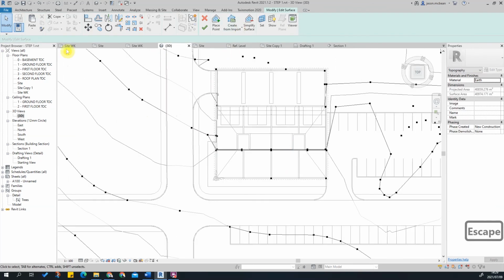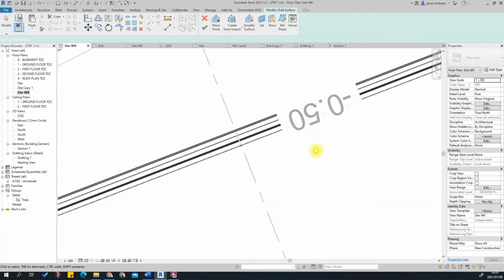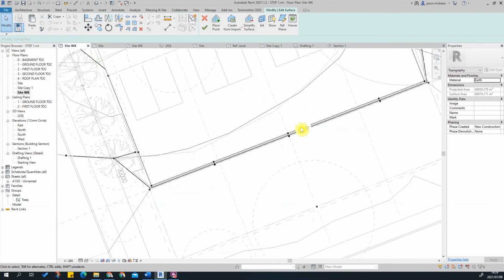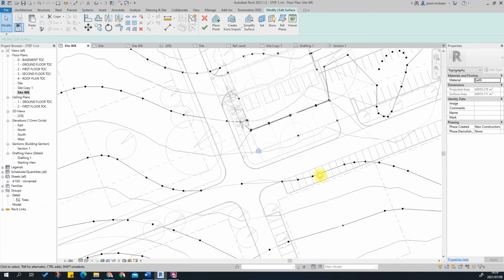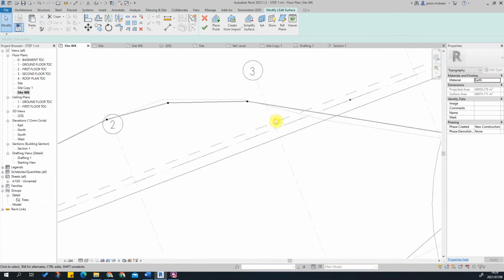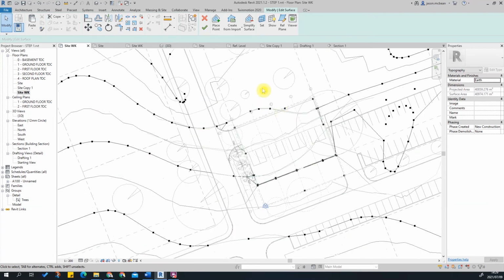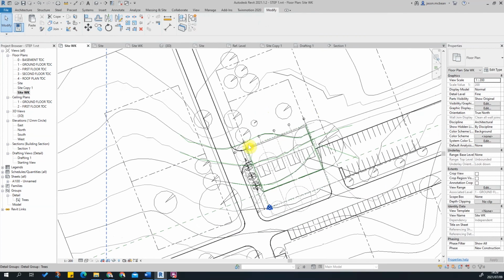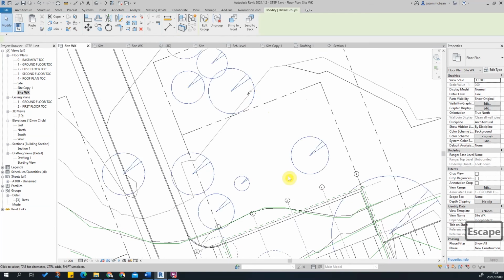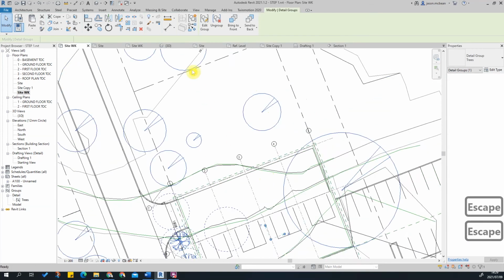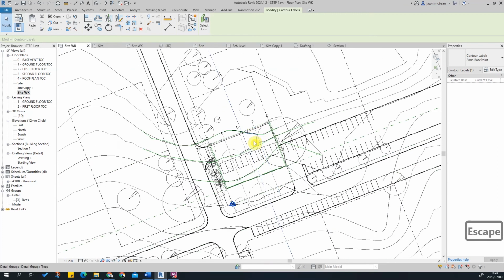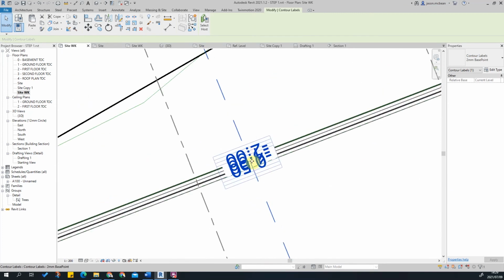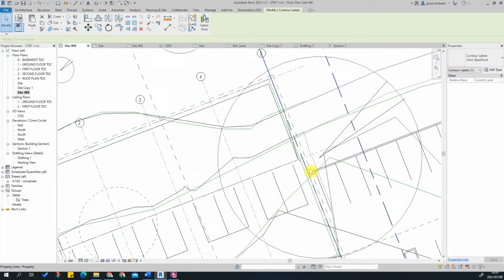Let's just go back to my site. That's 0.5. So we'll just see what other contour labels, they're all missing now, typical. Okay, that one's missing. Okay, let me just say finish. And this, oh, here's this contour label. So this one is a minus, why is this contour label not working? Should be visible there at -2 meters. Okay, here we've got a couple, -2 meters. It's just because we've generated a big hole here.